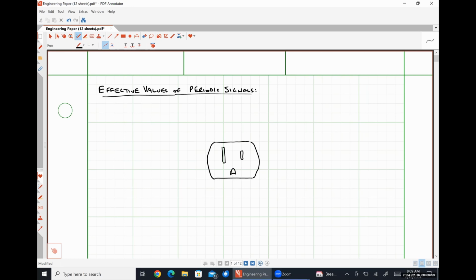Power in practically every industrialized country in the world is distributed using AC voltages and currents, okay? So when you see those large transmission lines when you're driving, let's say from here to Mississippi, those big towers, that's actually like 145,000 volts AC. It gets stepped down to around 13,500 volts AC at distribution substations, and then transformers are used to step it down even further for home systems.